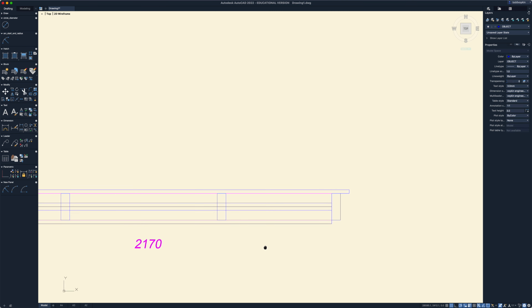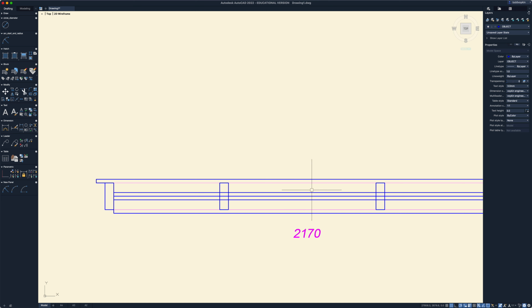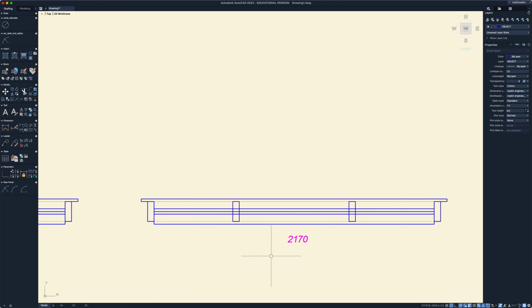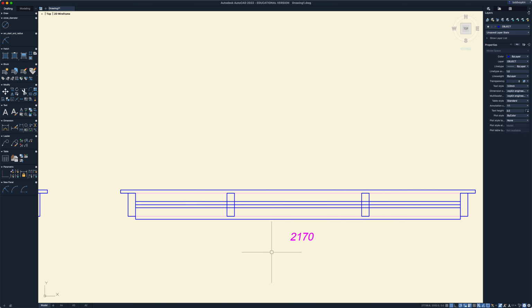Now the one in the middle here, that's going to be a fixed panel, and this would be an opening, but it can also be 3 panels that open up. Okay, so this could be 3 panels. If I wanted to say that this middle one was fixed, I'd probably leave it like that. If I want to show that it was 3 double hungs, so all 3 of these could open up, again, I would want to take these 3 lines and trim them out